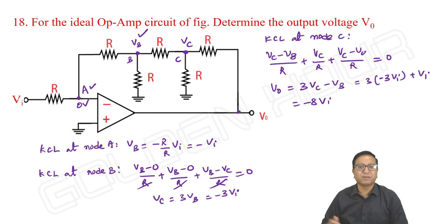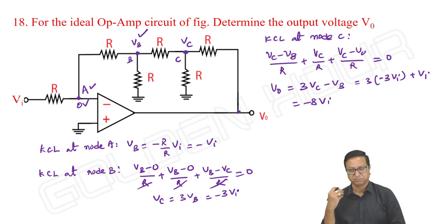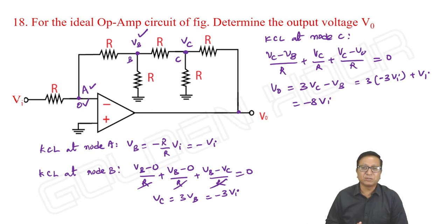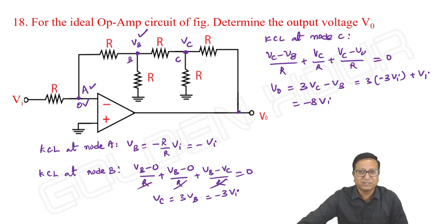Okay, like this you can proceed. That's why I told you we can blindly go with nodal analysis. Here, for my convenience sake, I took all equal resistors. The resistors need not be equal. Then also you can blindly follow this procedure instead of using star delta conversion, etc. This nodal analysis is much simpler.